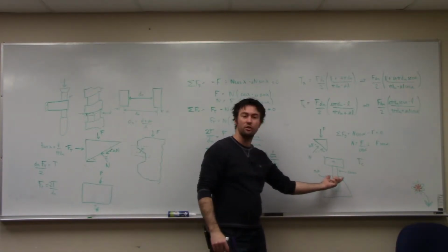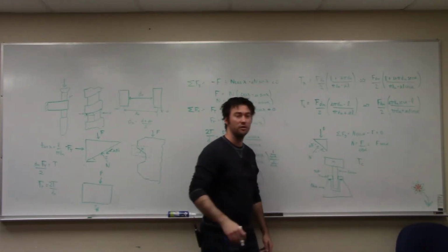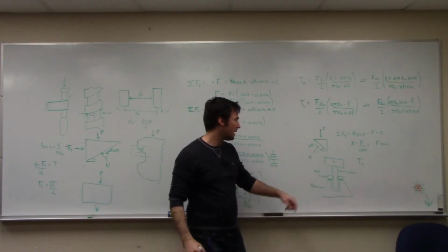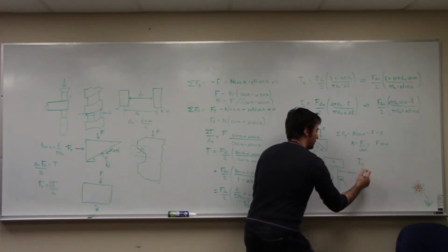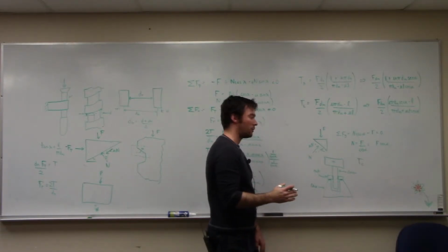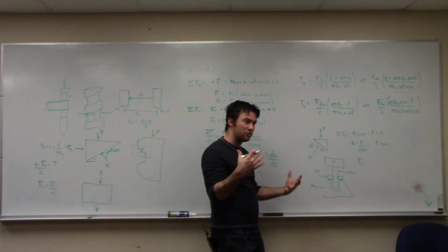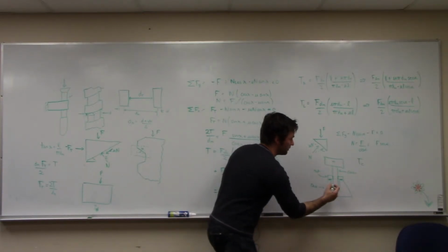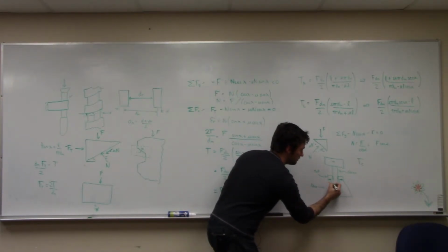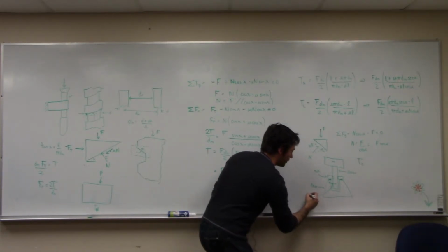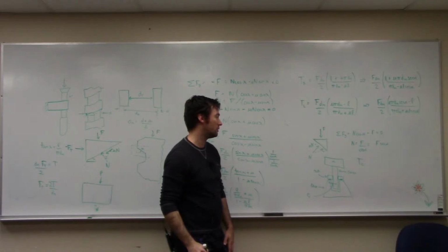We've got actually a pressure that's acting over the bottom edge of the nut. So take that force, and we're going to multiply it by friction coefficient. And that's acting at a certain radius, kind of halfway here. I can call this radius r of the collar, the effective radius of the collar.